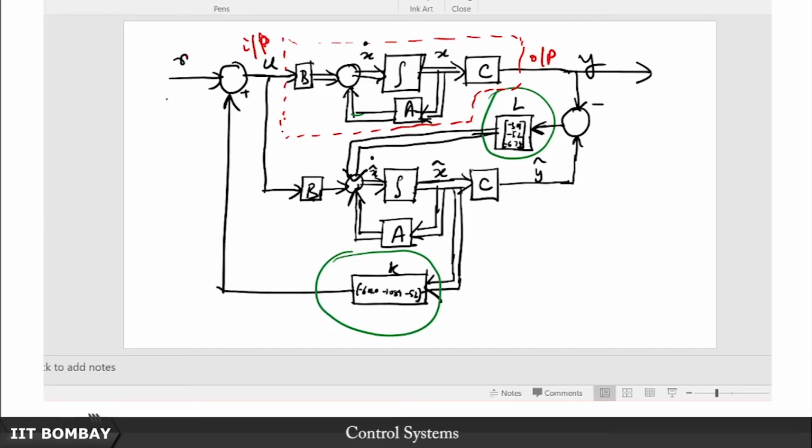With those synthesis tools we could only have designed controllers that achieve so much, but with the state space control method at our disposal, we are now able to design these systems in such a way that the poles can be arbitrarily placed anywhere on the complex plane, provided your realization is both controllable and observable, in other words a minimal realization. So that is what we have seen. Hopefully we have been able to paint a picture of what lies ahead, what the tasks are that a control engineer is supposed to accomplish.